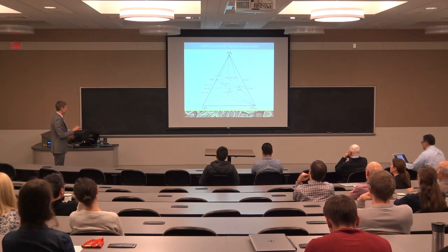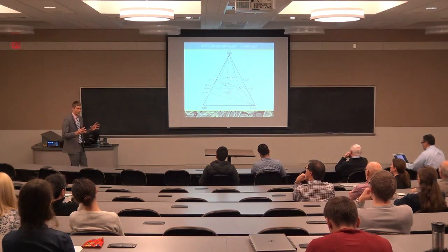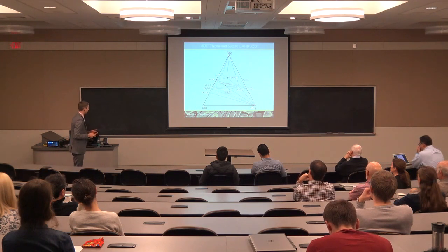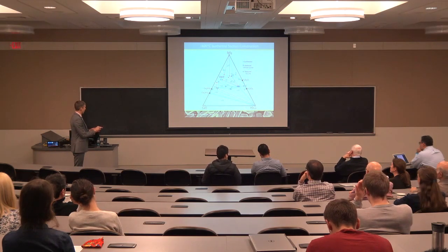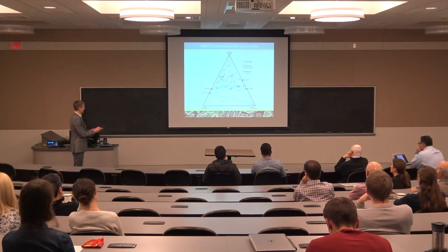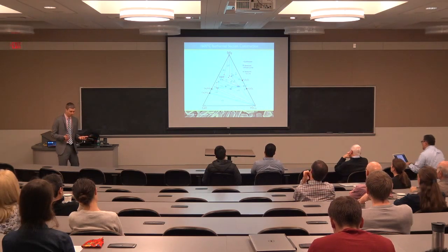And in the true systems, the addition of things like aluminum and magnesium to the system drives the eutectic down, and you get a much larger liquid field. But it gets complicated to study the equilibrium in a comprehensive sense when you've got 5 different oxide components. But if we go up in temperature, just in this system, we find that the liquid field expands, and we can then map out basically where the boundary of this liquid field is. In particular, what we're interested in is this 2-phase region between the apatite and the liquid.